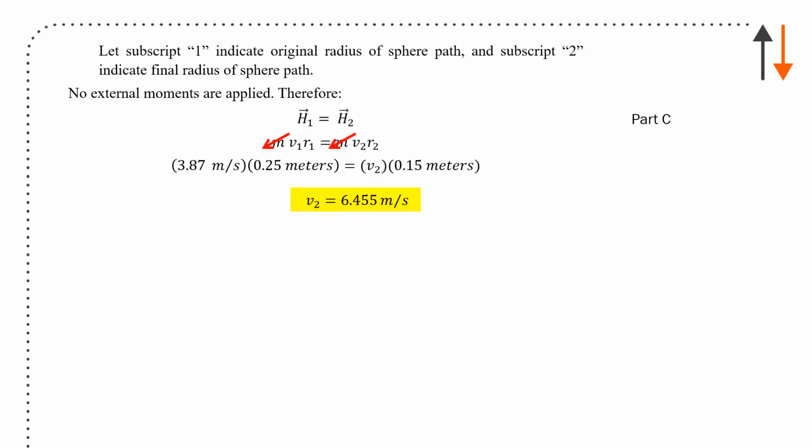If we say that we have the initial position 1 and the final position 2, and there are no external moments applied, then we have H1 equals H2. The two masses cancel because they're the same, so we can get rid of that term from our expression. We then have v1 r1 equals v2 r2. We know that the initial r is 0.25 meters, the final r is 0.15, and v1 is 3.87. The only unknown is v2, which is 6.48 meters per second.